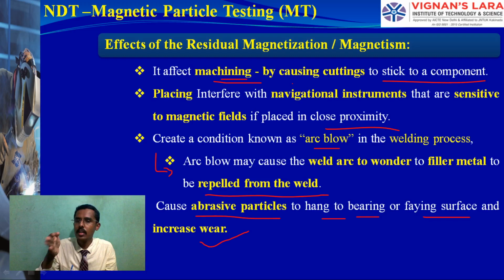So, method of demagnetizing. Initially, we created the magnetic flux for inspection, and now we have to destroy the magnetic flux. Yes, magnetic flux is created, and we have to destroy it also. By doing demagnetization, that particular material can be used without any residual magnetic field. That is the point you should remember: without any residual magnetism, it is as if it is very fresh.